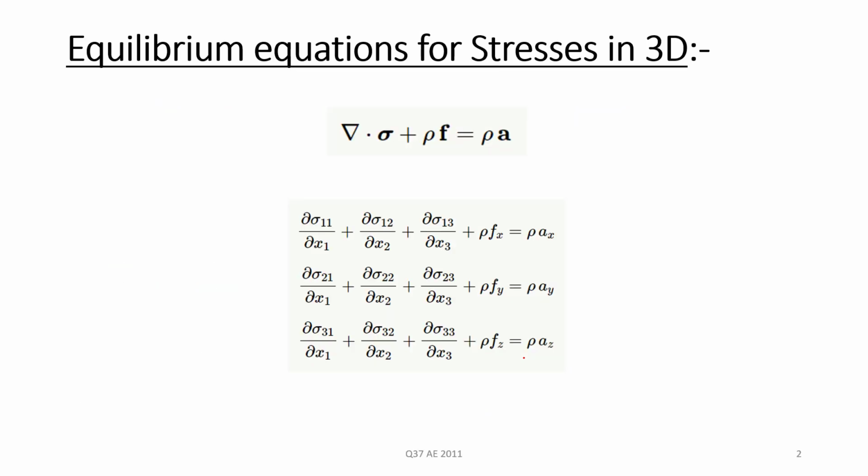First, we will see what the equilibrium equations for stresses in 3D are. This is the equation for stresses in 3D. This term is for shear stresses, this term is for body forces, and this is for mass into acceleration. So this is the net force, sigma F equal to m a. From this you can get this equilibrium equation.